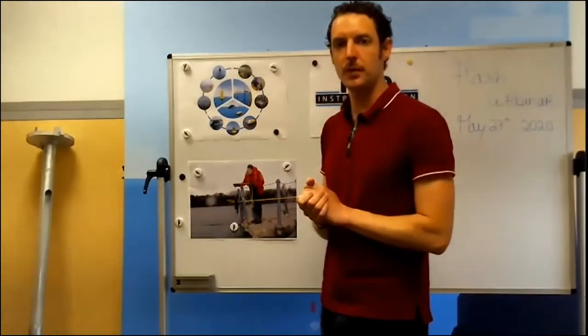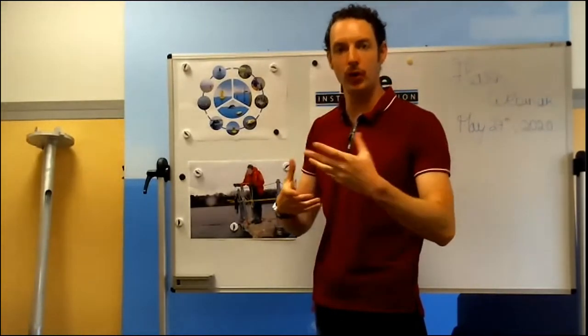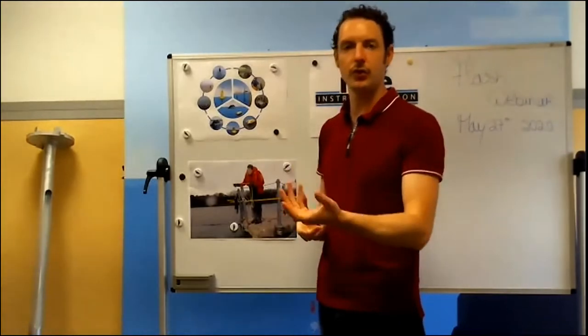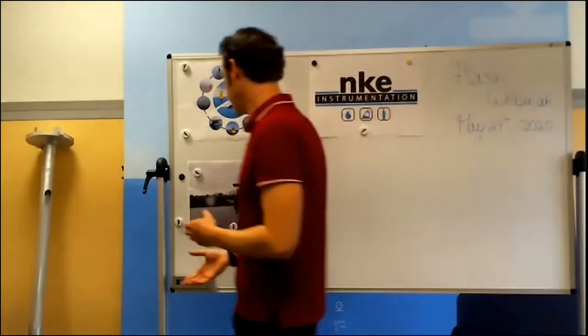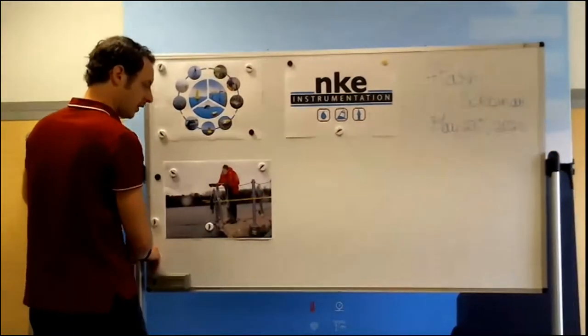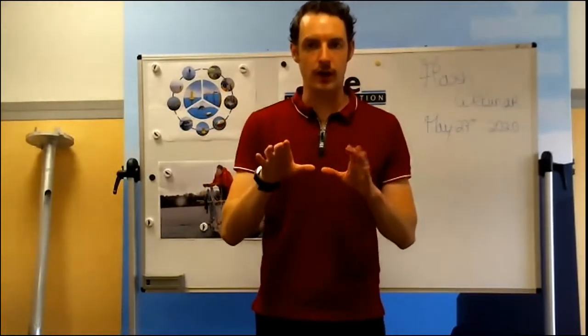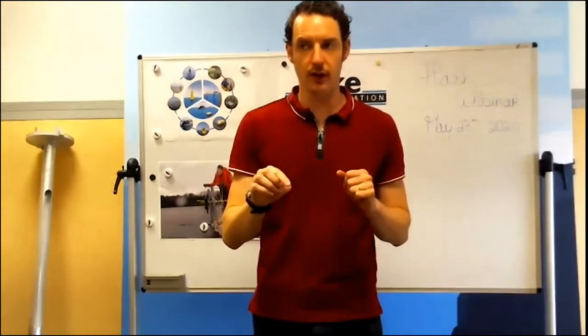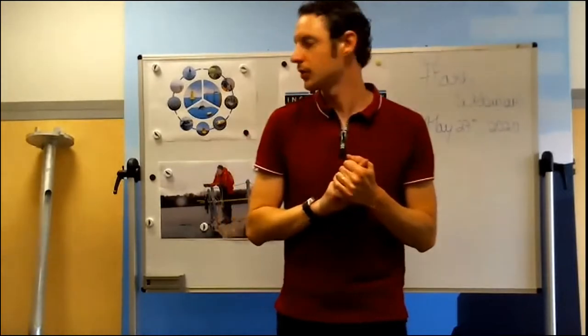The first one will be the one using start and stop modes, and I would say point-to-point measurements. Then the second one will be more focused on example of long-term measurements. So point-to-point measurements generally will ask for two types of programming mode of the sonde. Whether it's a manual mode, so you go in the interface, you click on start, you deploy the sonde, and you recover your sonde afterwards, and you click on stop. Or you can use a pressure condition.